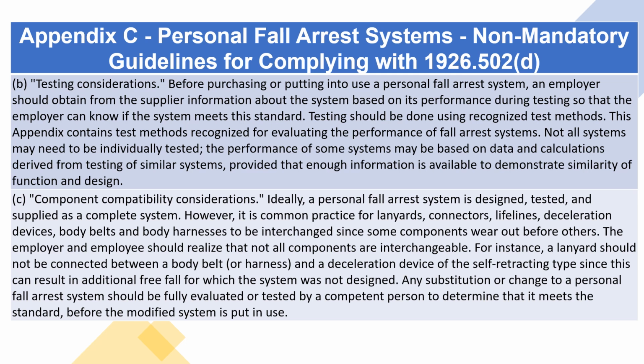Component compatibility considerations. Ideally, a personal fall arrest system is designed, tested, and supplied as a complete system. However, it is common practice for lanyards, connectors, lifelines, deceleration devices, body belts, and body harnesses to be interchanged since some components wear out before others. The employer and employee should realize that not all components are interchangeable.